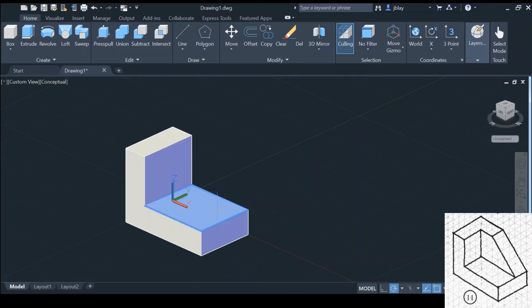And what I'll do is make sure that I'm hovering over this section because I want to make sure I'm drawing on the correct plane. I'll start at this corner here, and then I'll draw it to be over here. So it's giving me 3 axes, so be careful because that z-axis, that's height. I want it to go negative 1.5 inches by 0.5. Oh, I accidentally drew it in the wrong direction.